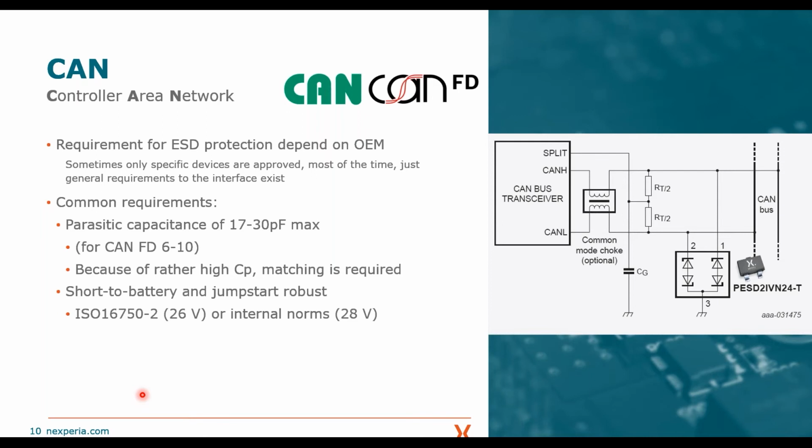So from the perspective of the ESD protection, there are similar approaches. There are car OEMs which have this approval list with specific part numbers which are allowed to use, and others may only give these general requirements on the network, and you choose the ESD protection device by yourself. But there are also some common requirements from the signal integrity point of view.